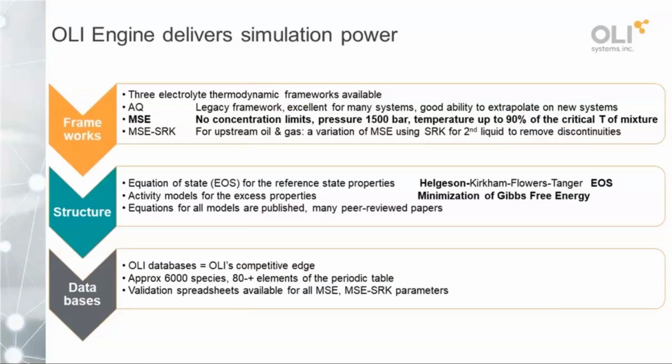Inside of the software, then, we have what we call three frameworks, essentially three ways to solve electrolyte problems or situations. The first is the AQ or aqueous model. This is our long-time framework. It's based on strong electrolyte theory, and it's good for a wide variety of systems. This is something we studied well over our history. The problem with AQ can be that because it assumes that water is the dominant solvent, we can't go to very high ionic strength mixtures, and so the model starts to break down.